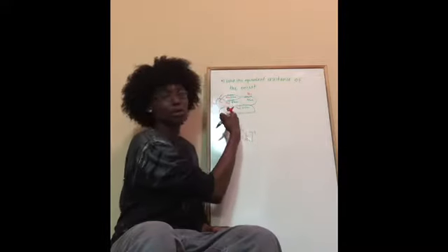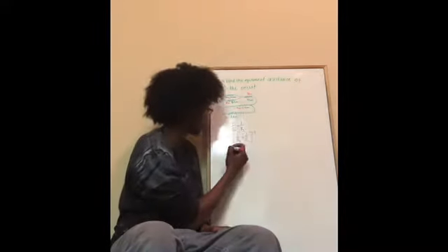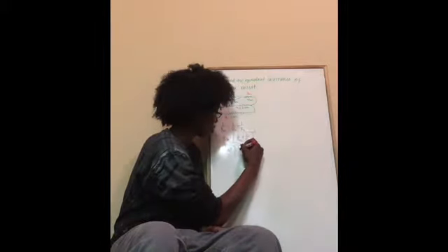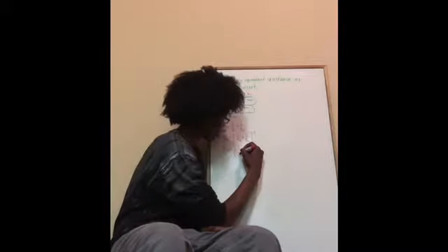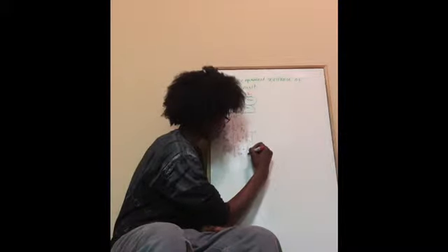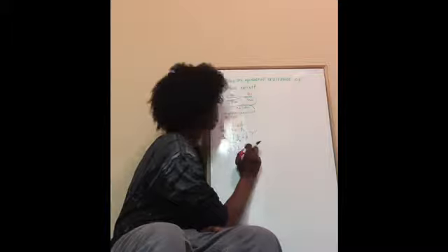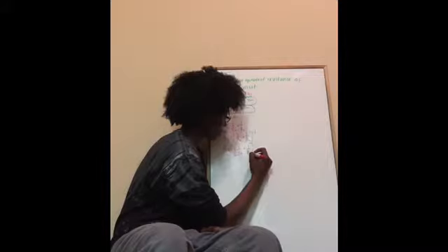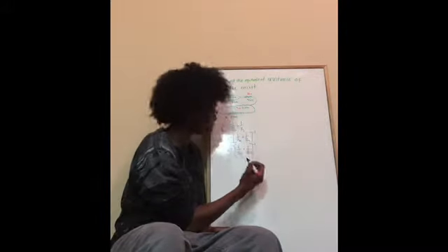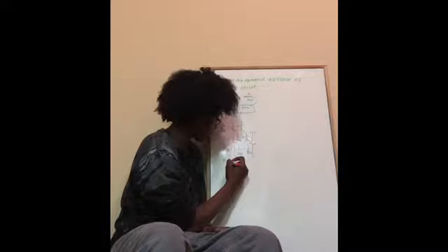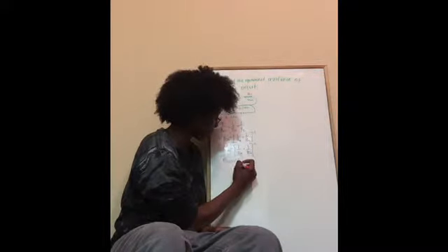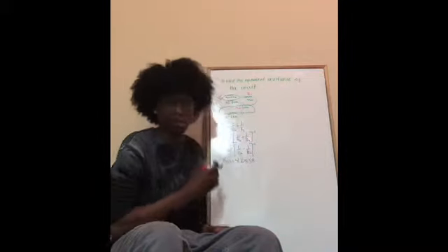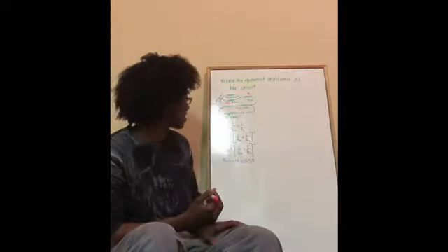So now we're going to go ahead and implement our values for our resistors here. So again, we have R23 is equal to 1 over R2, which is 11 ohms, plus 1 over R3, which is 8 ohms. And this is all to the power of -1 once more. So our R23 is actually going to come out to be 4.63158. And of course I did calculations before this.